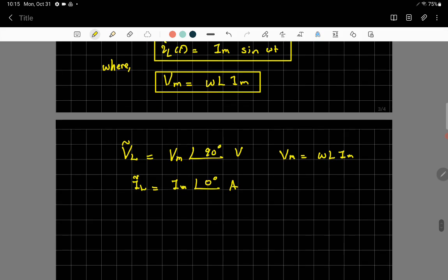How do we find the impedance? Refreshing our memory, in Ohm's law R is equal to V over I, but this is a special case. Now we're not working with that; we're working with something more general. Instead of R, write Z, the impedance, and use the voltage phasor over the current phasor. It's very similar. That's Ohm's law, the general one.